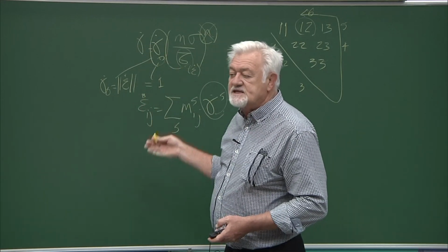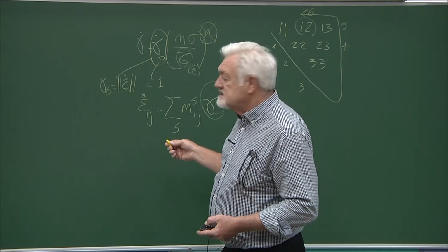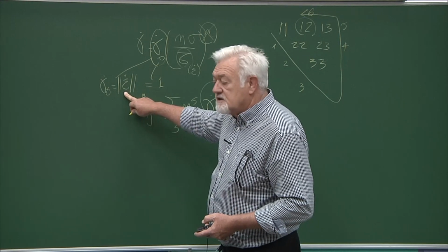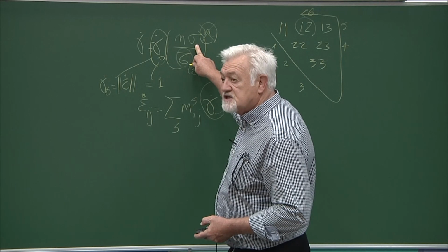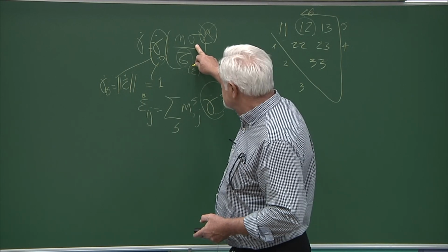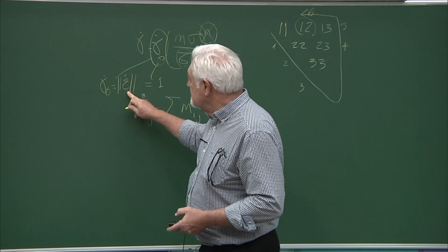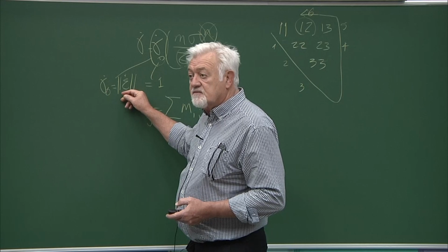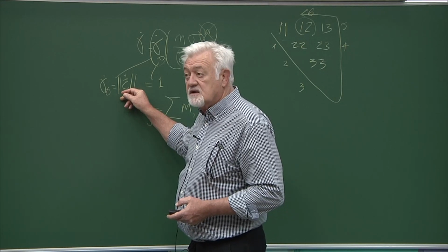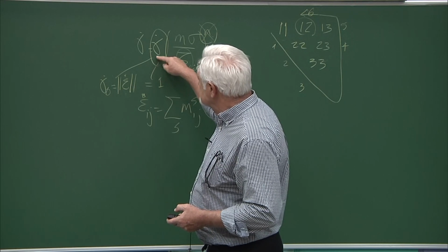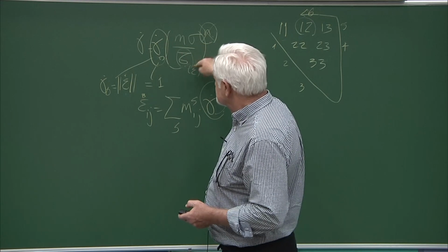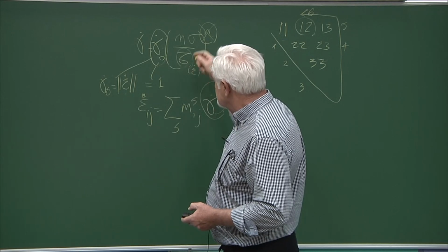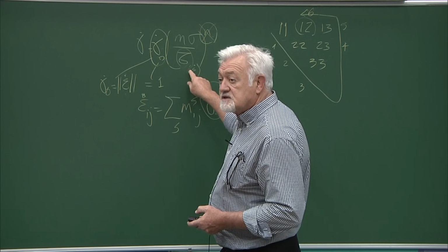And it is easy to show that in that case, the stresses are all the same, independently of what strain rate you apply, because this grows with the strain rate, so the stresses are all the same. But the dependence, if there is one, will come from this tau.